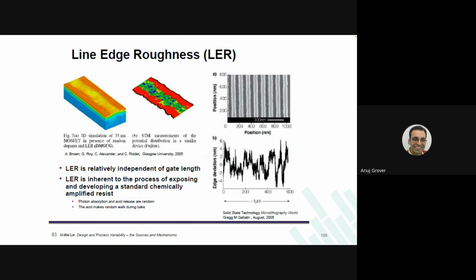It's discussed in lectures that line edge roughness is based on the anisotropic behavior. So we etch differently in the different directions. So this anisotropic behavior is not about the substrate. Substrate is fully crystalline. We talked only about the gate length varying at different places because the crystals could be placed differently. Crystal size could be different. They could be placed differently. Is it okay?